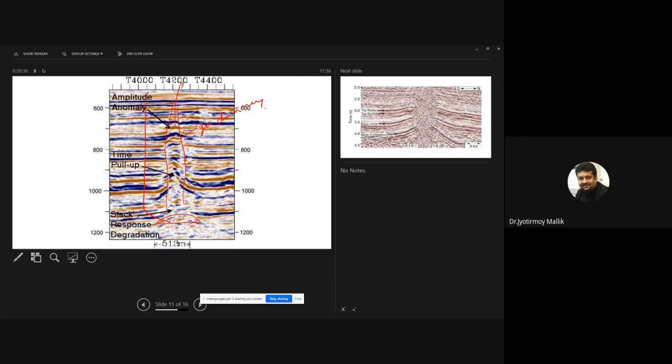Simply because this has inherent risk of carbon dioxide leaking, because there is geological proof that the oil and gas which was here has actually leaked through this gas chimney, right? So if in a reservoir we find there is already a gas chimney, I would not advise the company to push carbon dioxide back into the same reservoir, right?